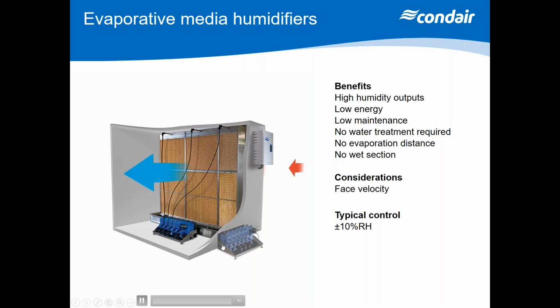But you have to remember that we have the dimensions of the tank and any blanking off around the side of the unit that is going to increase that velocity because we force more air through a smaller orifice, i.e. the face of the evaporative material. So on smaller units, face velocity can be a consideration.